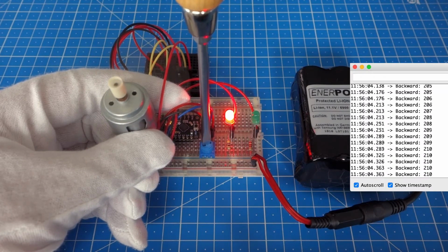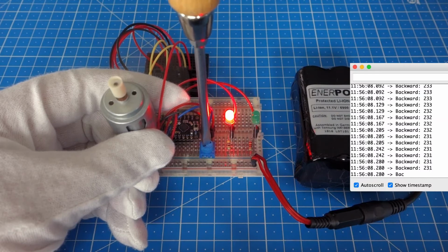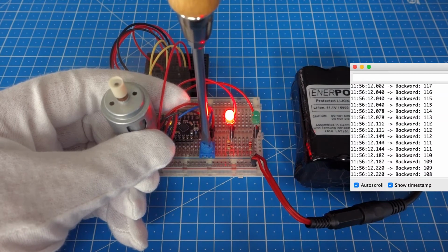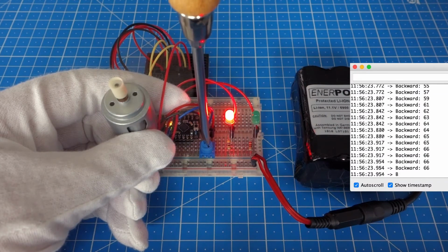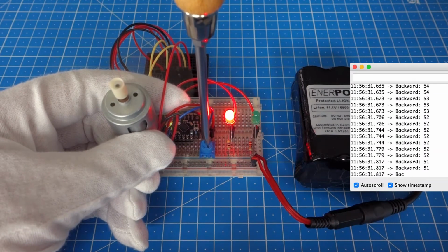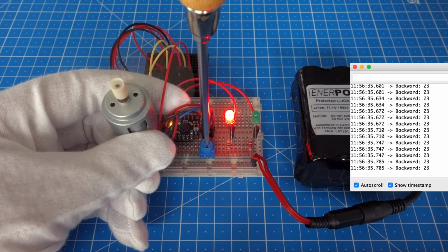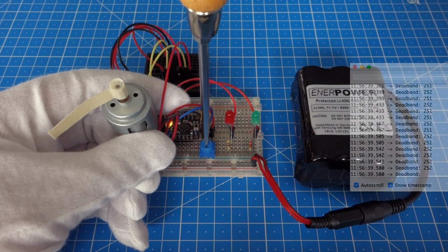As you rotate the knob towards the center, you are entering what's called a deadband, a zone of values where the motor is not powered. Without a deadband, it would be difficult to have a clearly defined halfway position where the motor is off. You must also use a deadband with joysticks, because joysticks are twin potentiometers. Look at the code with detailed explanations for how this is done.